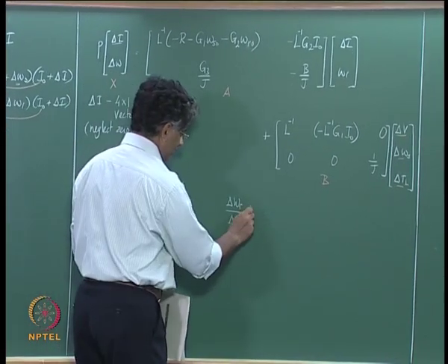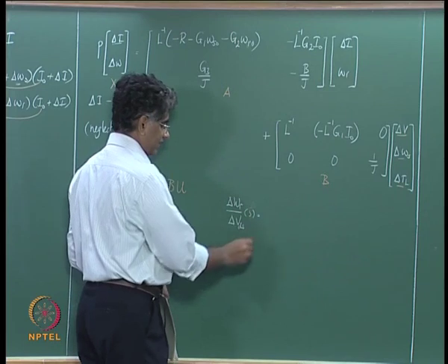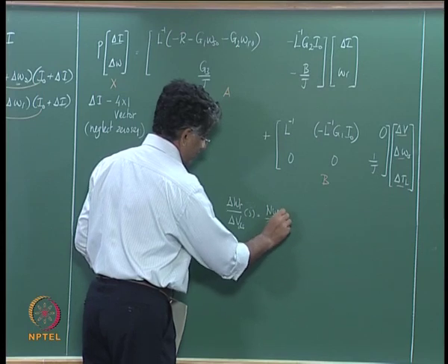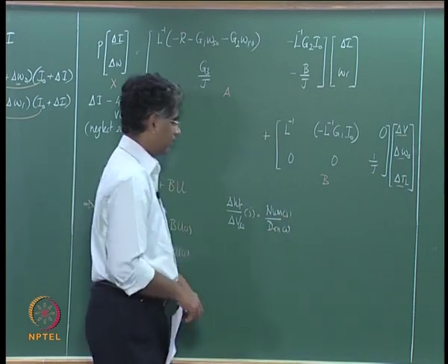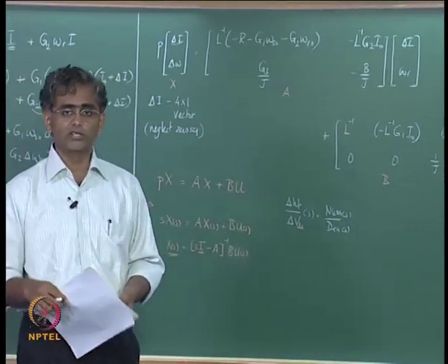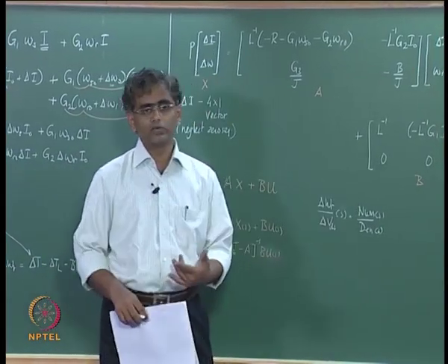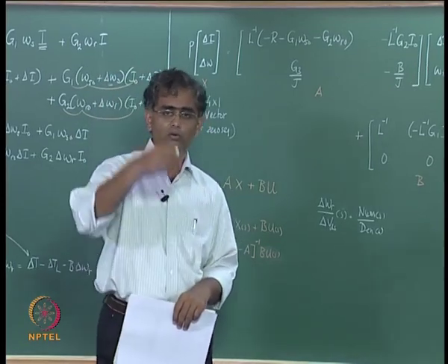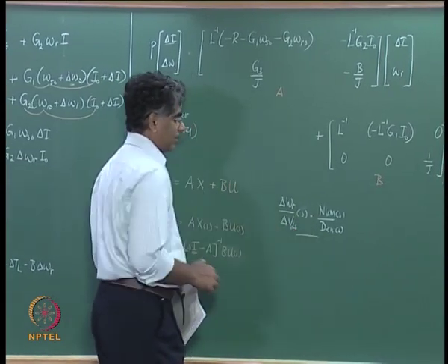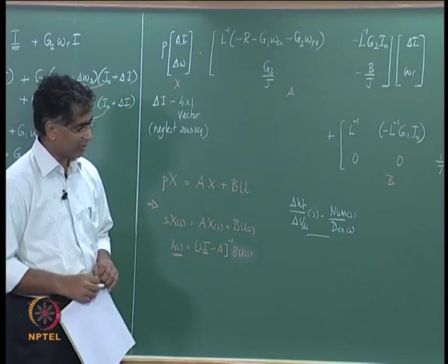So this is then described in terms of the Laplace variable s, and so you get some numerator by denominator both as a function of s. One can then look at the roots of the denominator in order to find out how this is going to change with respect to time. As usual, the numerator function also gives you more information about the amplitude of the overshoot, etc. So one can do similar analysis as we had seen in the DC machine using this small signal representation.